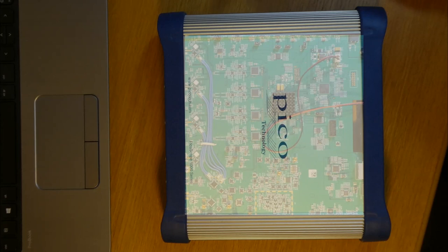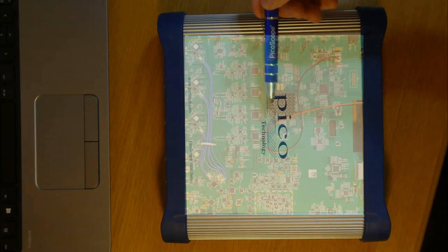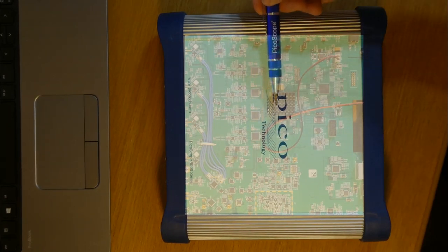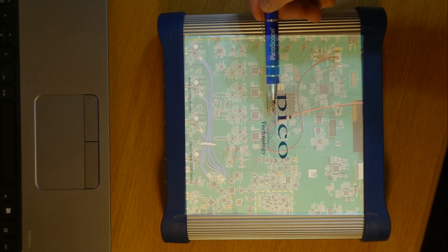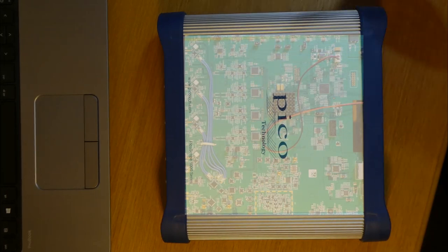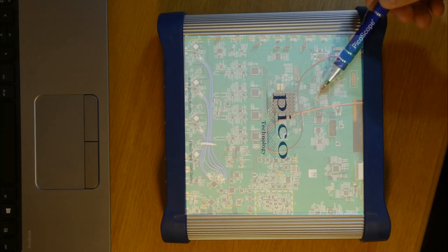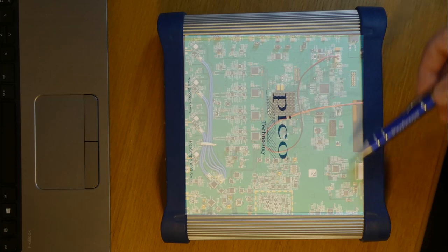Converted sample data routes back to this large format Kintex FPGA, that features Core SRAM, which we're using for our trace stores. The whole instrument is supported by this ARM processor back here, and then USB and LAN interfaces down to bottom right.